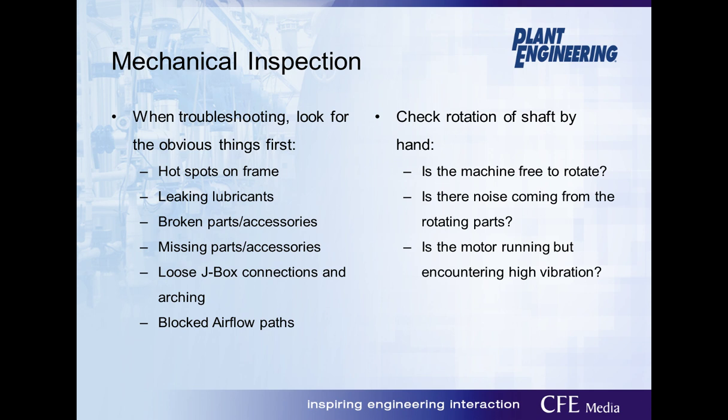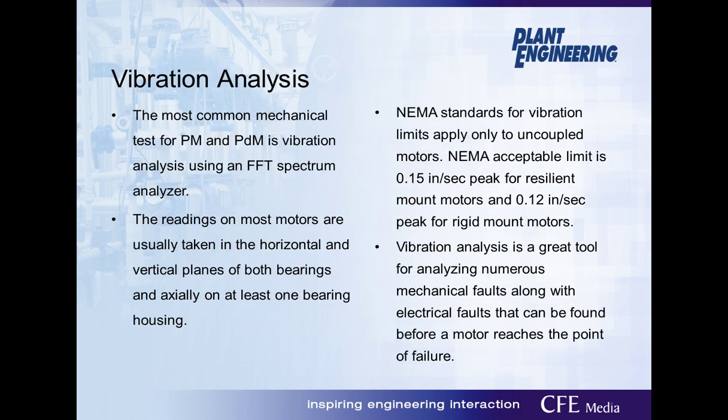In some cases, you're expecting a mechanical issue before it becomes a failure. You notice high vibration coming from the motor, but not very clear on where the source is coming from. In this case, you can perform vibration analysis. Vibration analysis is the most common mechanical test for preventive or predictive maintenance. This test is performed by using an FFT spectrum analyzer and using an accelerometer that is usually placed in the horizontal and vertical planes of both bearings and axially on at least one of the bearing housings.